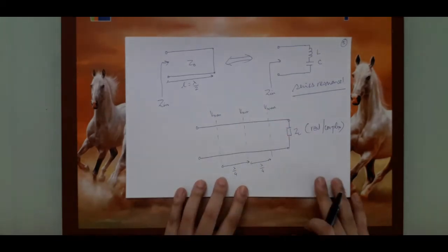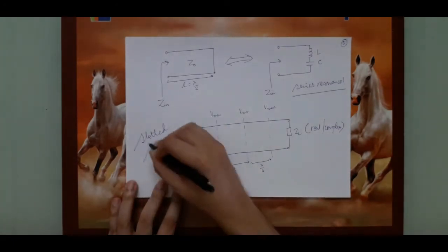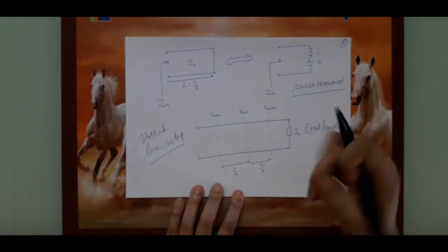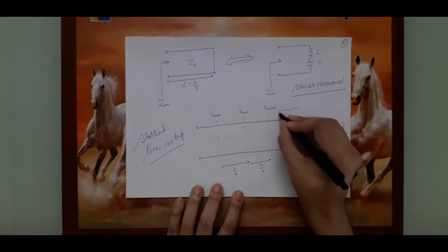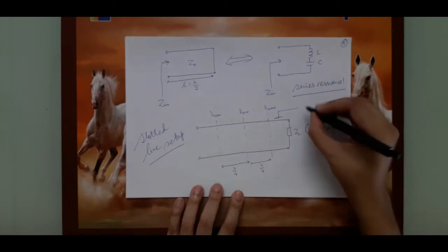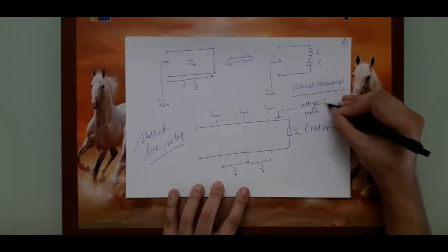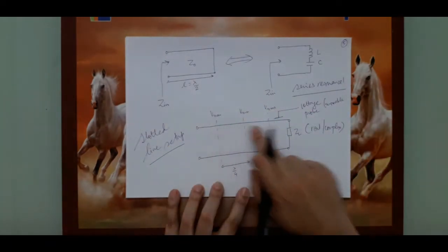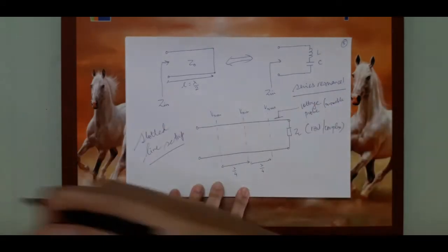The way to measure these voltages is to use something called a slotted line. Here you take a voltage probe and move it along the line, but you don't physically touch the line. You have a voltage probe which is close over here, which is movable. You can move this voltage probe along the line where a small opening is made, called a slot, for the probe to move.